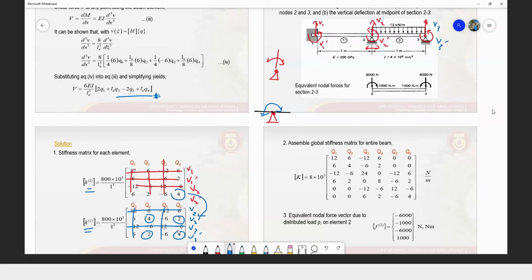So your matrix, instead of 1, 2, 3, 4, 5, 6 because you have 6 degrees of freedom here, not all are active, only 4 are. So the active ones are V2 prime, from V2 prime, with V3 prime. So all the others are inactive. So you can actually eliminate all of these. So the only ones left are this and this and this, with the one in front of it, don't leave it out.